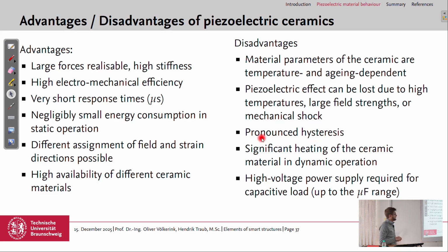We have a pronounced hysteresis, which we neglect in the small signal behavior. And we have significant heating of the ceramic material in dynamic operation, which also comes from the hysteresis. And we need, as we saw yesterday, a high voltage power supply to drive the piezo ceramic.